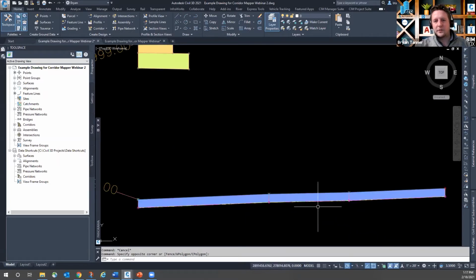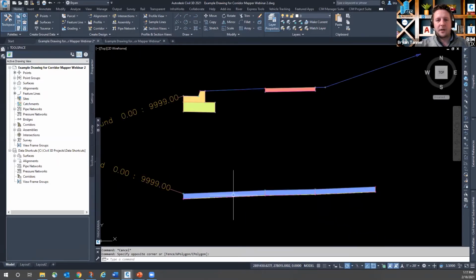And this is more than just a little basic drive. It's actually the drive approach with a flattened out 2% section for where we overlap with our sidewalks. So we retain ADA capability and compliance. And then a drive that's going to ultimately daylight out to your existing right of way, if it's a reconstruction project where you're building out your drive approaches to the right of way limit or to whatever set elevation you have for your site grading.